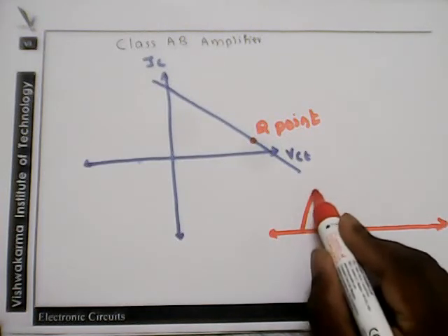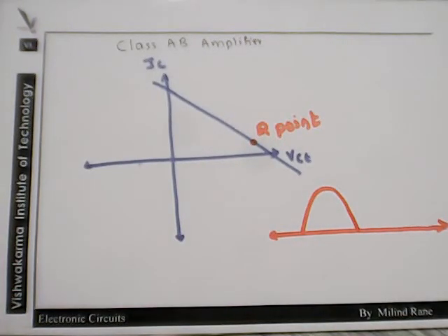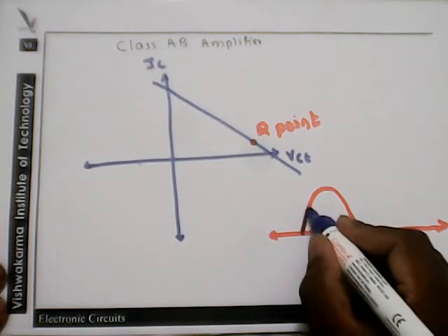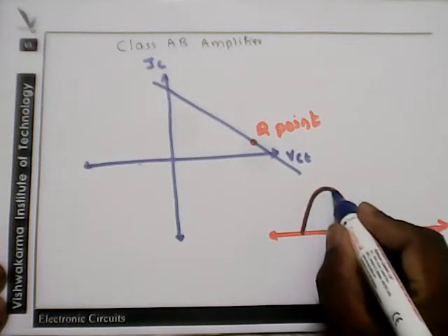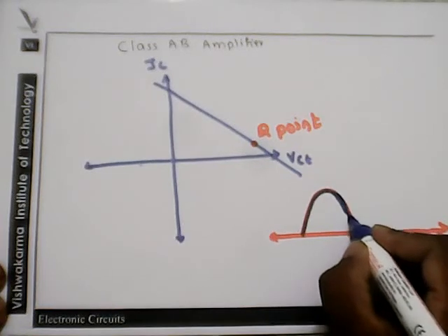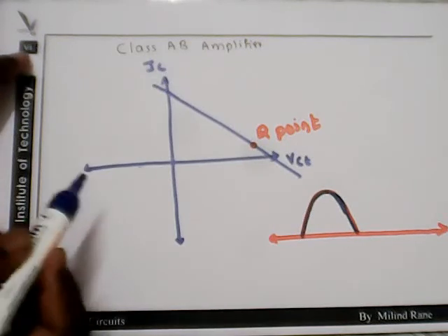During the positive half cycle, as the transistor is already turned on even if the input signal is equal to 0, we get the output following the input as it is here during the first half cycle. Whereas for the second half cycle, the negative half cycle, there is another transistor, for which the operating point will be like this.